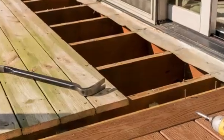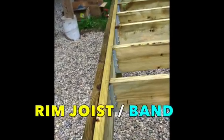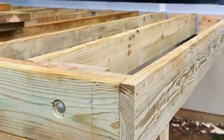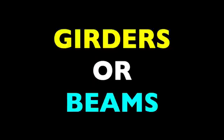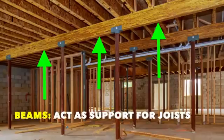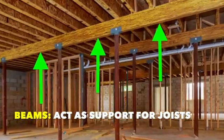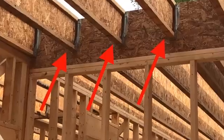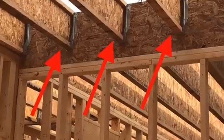You still see a lot of dimensional lumber on job sites, especially in outdoor structures like decks. The outermost joist in a floor or deck is often called the rim joist or the band, depending on application. Other joists pair up with it or run into it. Sometimes joists are even supported by another horizontal framing member called girders or beams. Beams tend to be bigger, stronger pieces of lumber that act as a spine for joists to sit on. They're sort of like super joists for other framing members. Sometimes joists even run straight into them and are held on with hardware.